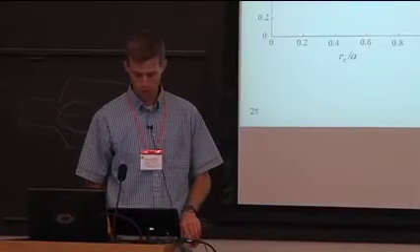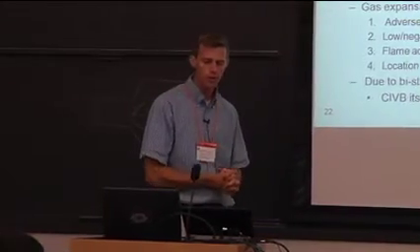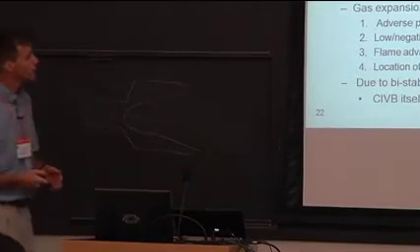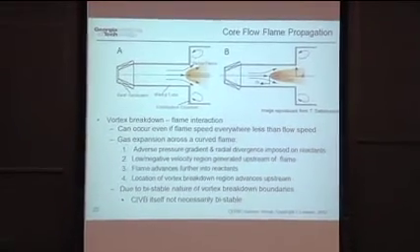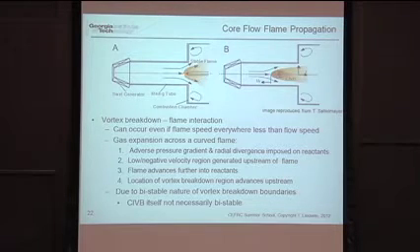Again, I'm just going to jump over this because I'm talking too fast, but too slow. I showed you some intermediate calculations, but I'm just going to jump straight to the essence of it. And by the way, Thomas Sattelmayer at Munich has done great work on helping us better understand flashback, and this is pulled straight from his stuff. And here's the idea: I have this flame, just the picture I just drew here. And again, it's a positively curved front with gas expansion, which causes the approach flow to slow down. It imposes an adverse pressure gradient.